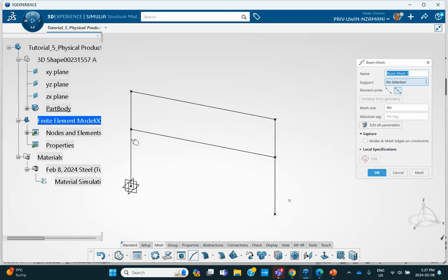When I join it, then at the juncture you mesh it at the junction, you have a unique node. In tutorial 2, I did not actually join it. I drew this thing as wireframe, just like I did here. However, I checked this box, which said that if there are two nodes that are within a tolerance of each other, then merge them. That was tutorial 2. And in tutorial 3, I did exactly what I'm doing here, except that it was a one-story build. So I'm not going to do that.